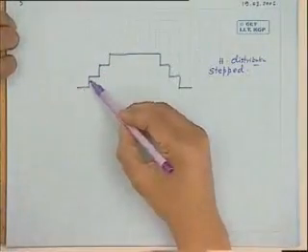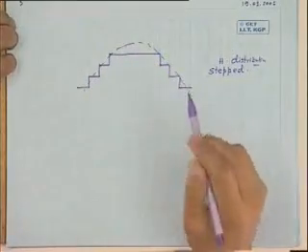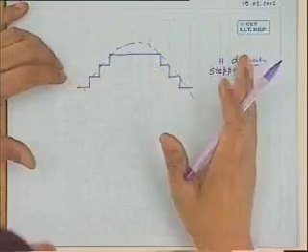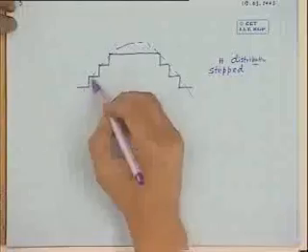But this one is far better. This one looks more like a sinusoid already. If you Fourier analyze it, its fundamental component will be quite strong. There will be, of course, in this case several other harmonics. But it is certainly better than this option, instead of using a single coil to produce a flux like that. In fact, we will deal with the fundamental component alone at this stage, and we will see later, if there are harmonics, how to avoid the effect of harmonics either in the induced voltage or in the calculation of the torques of a machine.